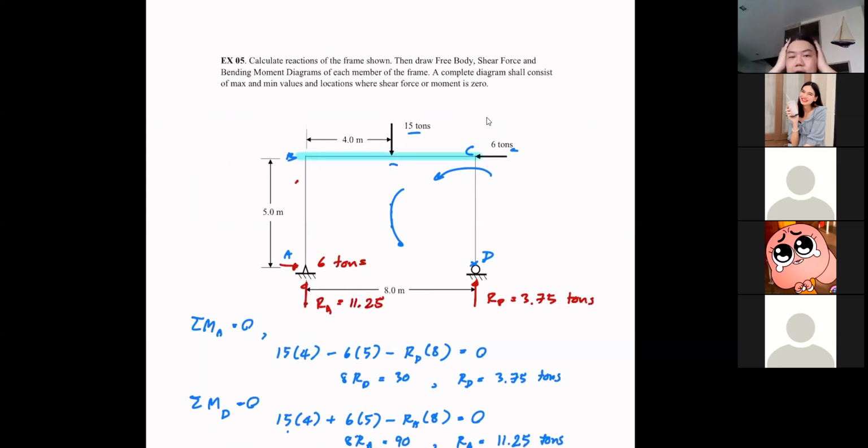So let's say this is a frame in a factory, and it is going to be made of steel, just like the picture that I showed you. Generally, a steel member is fabricated or manufactured so that each member is only 6 meters long. They can make it longer than that, but it's going to be a problem with readjusting the equipment and especially the transportation.